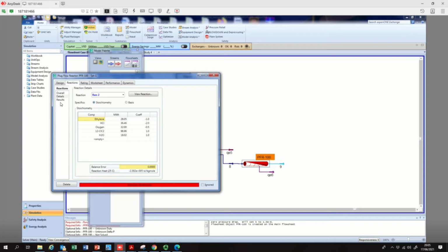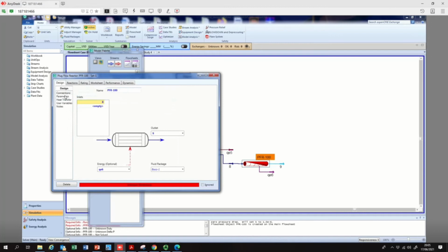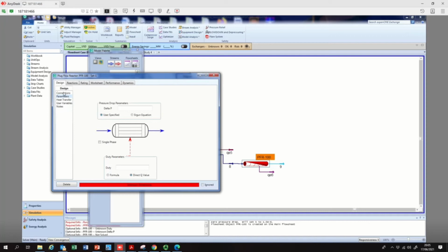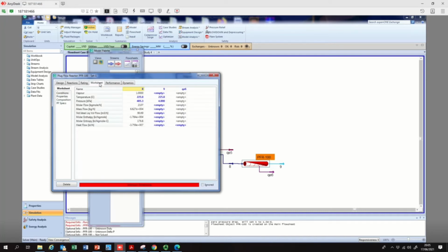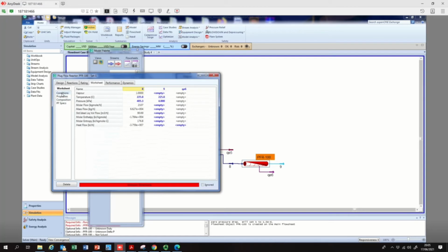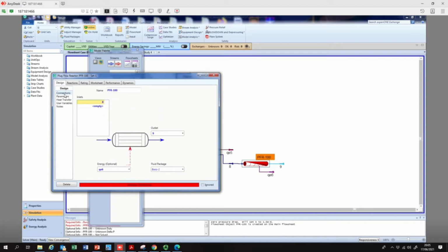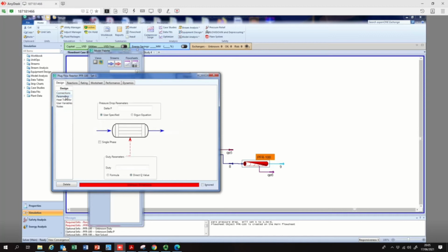Okay, so what we do is let's begin with some number. So go to design, connections, parameters. Temperature, pressure, molar flow rate. I'm just checking where is the information to enter the volume. We have to enter the volume of the reactor. Connections is here, parameters.